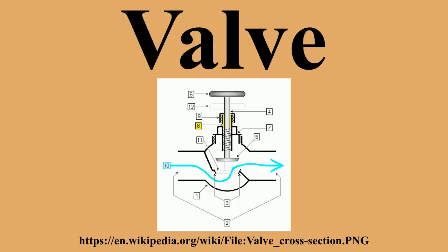Trim. The internal elements of a valve are collectively referred to as the valve trim. According to API standard 600, steel gate valve flanged and butt welding ends, bolted bonnets, the trim consists of stem, seating surface in the body, gate seating surface, bushing or a deposited weld for the back seat and stem hole guide, and small internal parts that normally contact the service fluid, excluding the pin that is used to make a stem-to-gate connection.